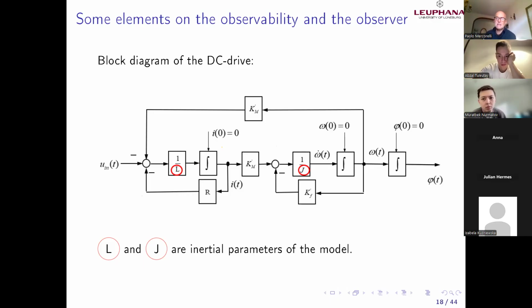Km equal Ke in our motor. This is a structural condition. At the beginning I told you about Ke, but I put Ke equal Km. In any case, because of this back effect, which is the name, a little bit more complex, I will have here also information about omega. This is intuitive. We will see mathematically what is the meaning. But I don't have here, and this scheme is important, information about phi. It's clear because we don't have physical feedback, structural feedback, or structural connection.